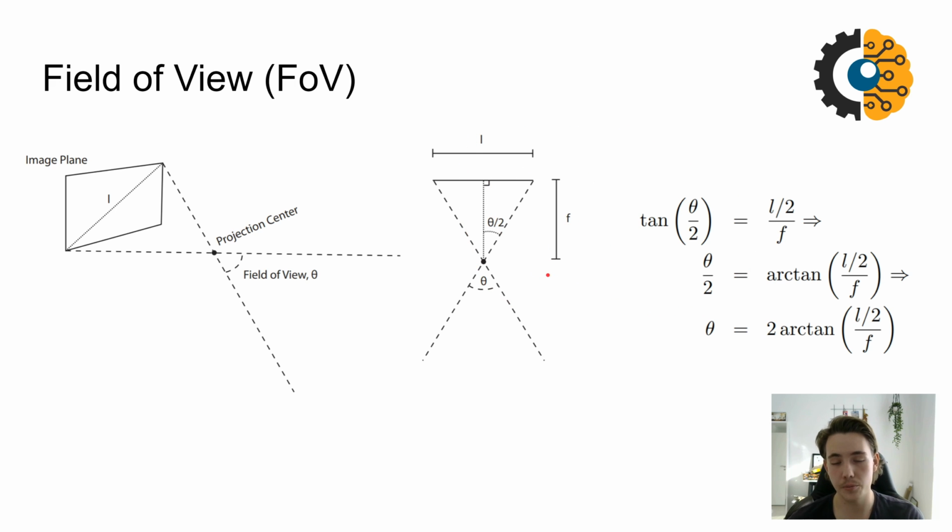So we can use this for camera geometry as well, where if we want to estimate where some point is in the image compared to the center axis here. So let's say we had a point here, then we can use this optical center here and the length up here. The length from here to here would be half of this length up here, and then we can estimate the displacement from the center to the point in our camera, and then we can estimate that angle to the object that we can see in our camera. So we can use this to estimate angles and also estimate how far away that object we have detected is. So it can be used for a lot of different kinds of things, and it's also just good to know basic stuff about field of view when we're going to talk about camera calibration as well.